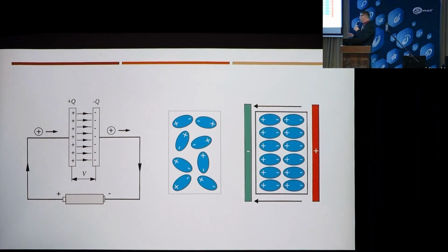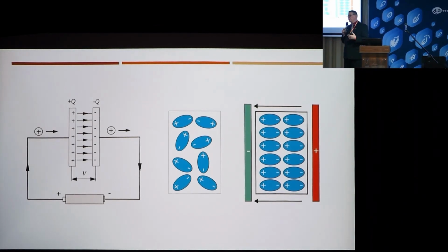The first thing is capacitance. Obviously, we were talking about low voltage installations, but the capacitances there are small. They really get charged almost instantly. Besides, with a 500 volt test voltage in most cases, if the object is in good condition, you'll get a result that says over range.